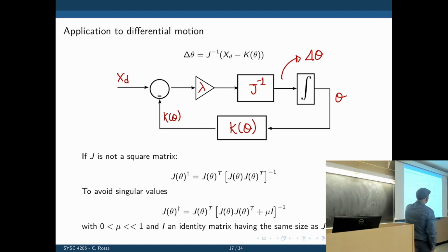So what is interesting about this is that we didn't use the inverse kinematics at all. We let this run several times, and the result is the set of angles theta that minimize the cost function. There is no guarantee that the error will be zero, right? But at least it provides a valid solution that will approximate the end effector to that desired position.